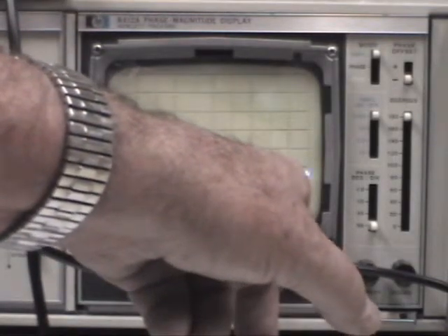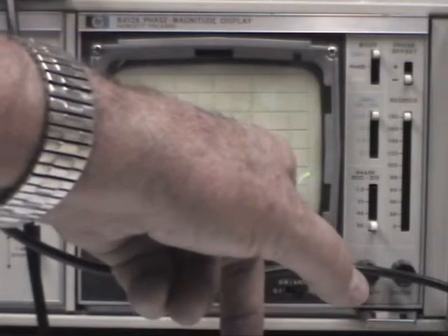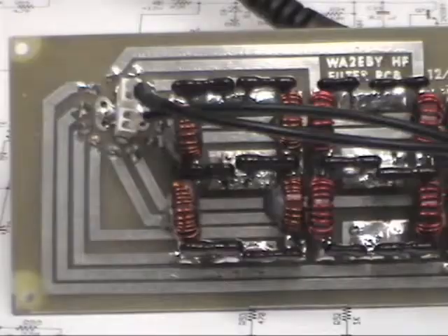I've got longer cables than I should have to do an accurate measurement. This is about 100 meg, so we're not going to worry a whole lot about that. This is down a little over 1/4 dB, so I'm getting some roll off through those particular cables themselves. But that won't bother us for looking at the filter.